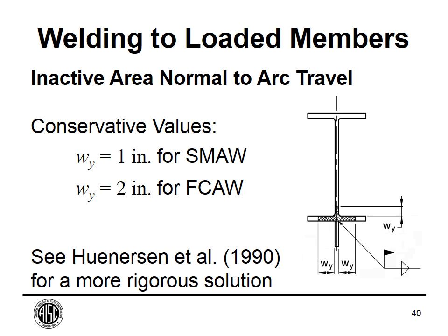And always go from the opposite side of the element that you're welding, like the top flange of the beam here is where I measure my W sub y, or this side of the plate if you're going in this direction. So use W sub y in all directions of 1 inch and take that chunk out of your beam or column, whatever member you're welding to.